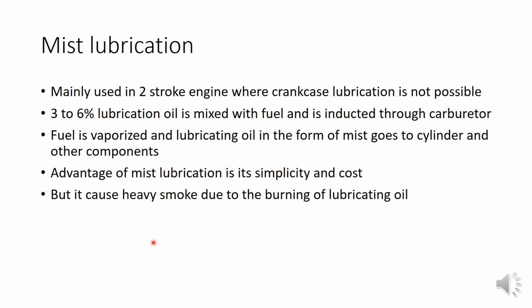One is, some of the lubrication oil will be burning since it is inside the cylinder. The combustion of lubrication oil will happen, and it will result in heavy smoke. So this is also one of the reasons why two-stroke engine emissions are more. There is a chance of burning of lubrication oil, which is very undesirable, and it will produce heavy smoke. So that is one disadvantage.